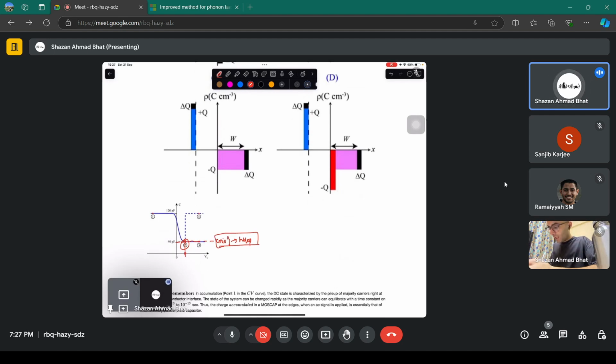Okay, this particular gate voltage here is the threshold gate voltage, at least at that particular point. Right at that point, inversion has just started to happen. It has not happened yet. At threshold voltage, it just starts to happen. When the gate voltage crosses the threshold voltage, you have the inversion. Okay, so at point number 2, you still have the depletion region, but with maximum depletion width.